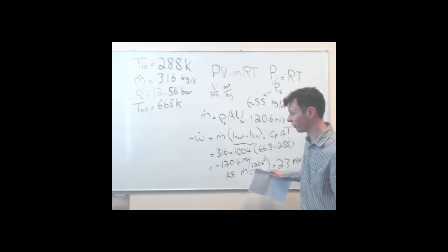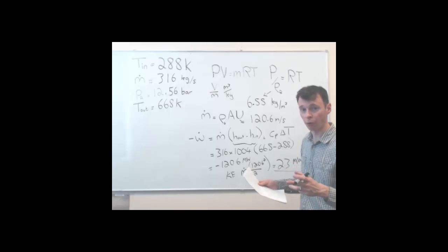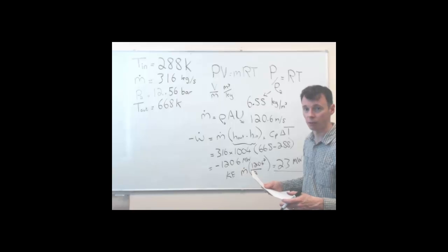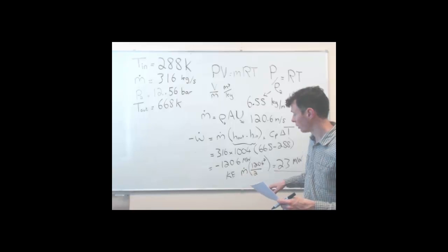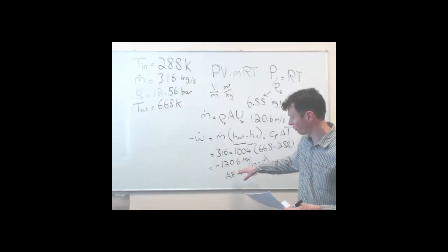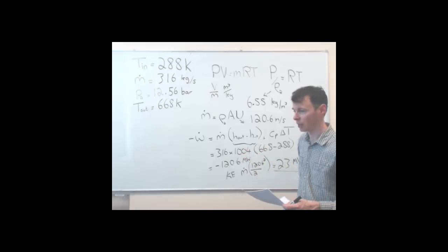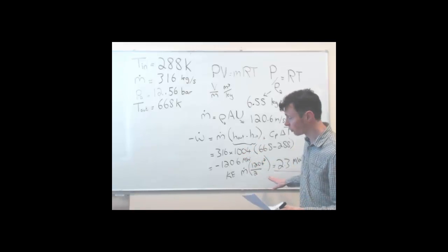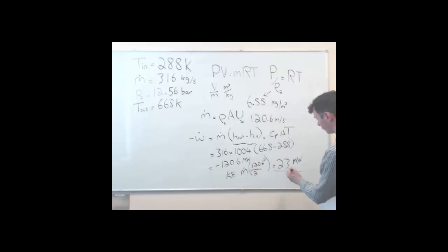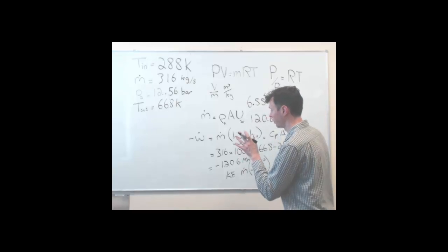If we're doing a lot of work on the gas in terms of changing its enthalpy, either through a work input or heat input, quite often that amount of work or heat is massive in terms of the total energy. So it's by far the largest proportion, and any kinetic energy in or out is really quite low. It's always useful to do a check though, and just make sure. So 2.3 megawatts, so only 2%. Okay, so now we've found the first part.